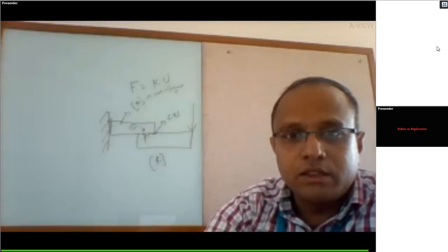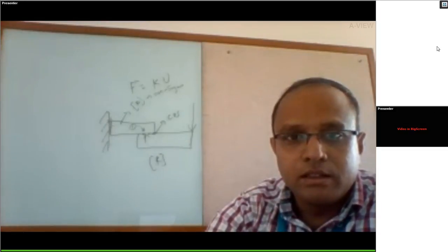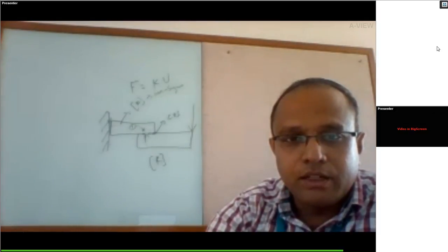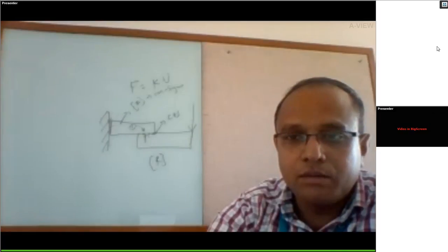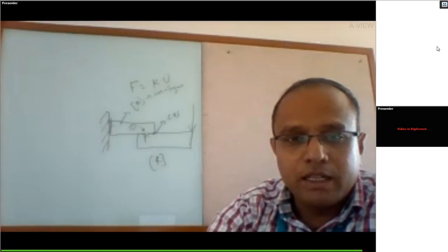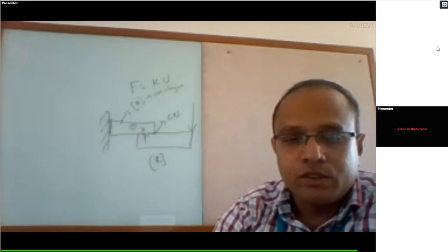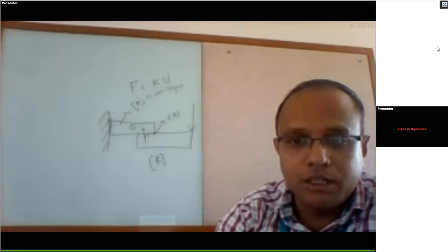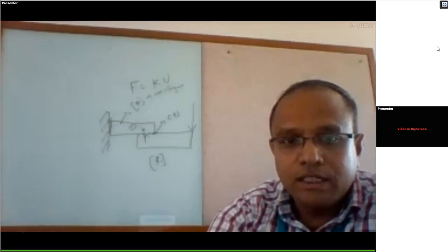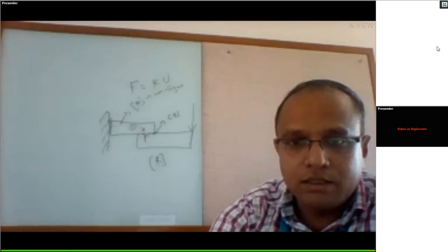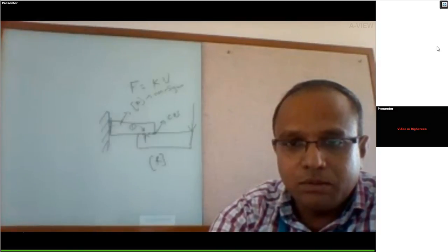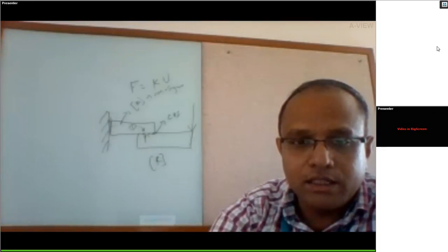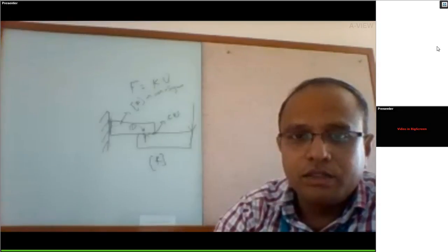Constraint equations are used for a variety of applications: connecting dissimilar meshes, modeling interference fits, connecting meshes that have different degrees of freedom, that is, connecting shell and brick elements, and modeling rigid regions. One example is connecting components with dissimilar meshes. Here this part is a brick mesh and this part is a tet mesh. Definitely we cannot establish a coupling here, so we need to go with a constraint equation. We used a constraint equation and solved the problem.